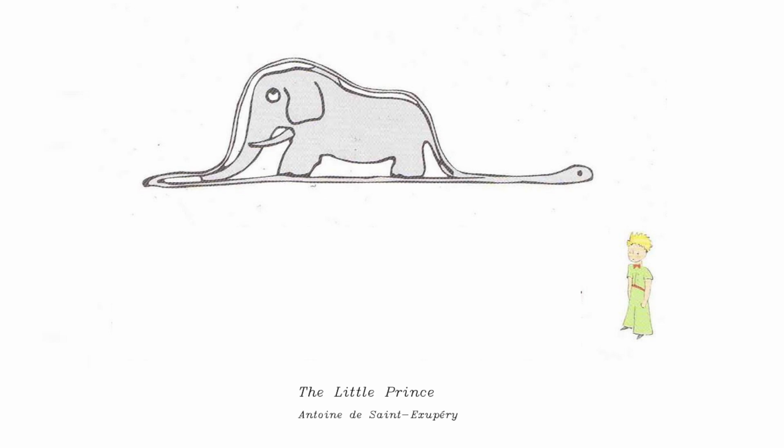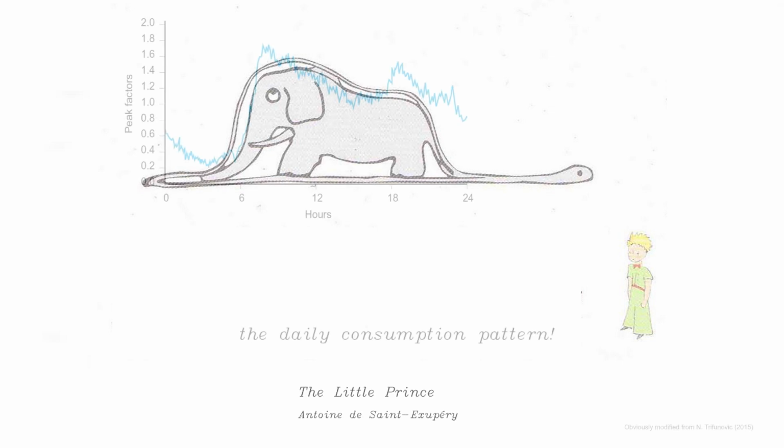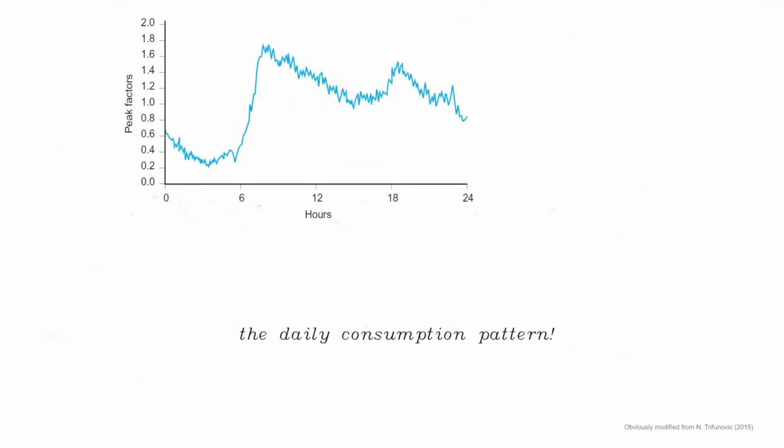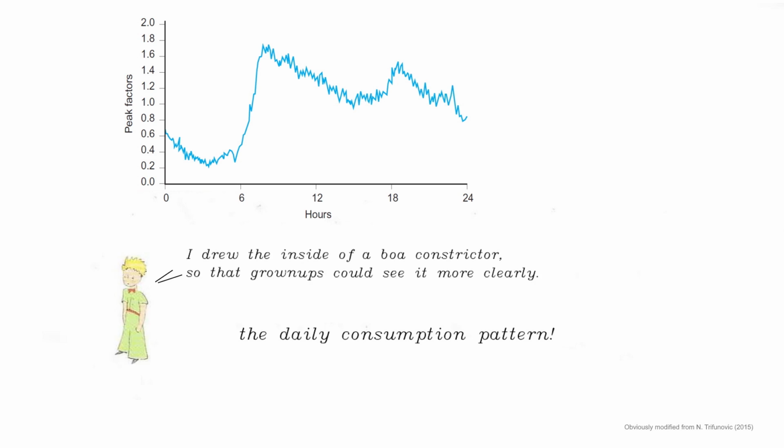We start with the daily variations. They reflect the changes in water use as people go about their day. In my mind, they tend to look like elephants, with a big round peak in the morning, a midday plateau, and a smaller peak in the afternoon. Nighttime consumptions are usually low and can be a very good indicator of leaks.